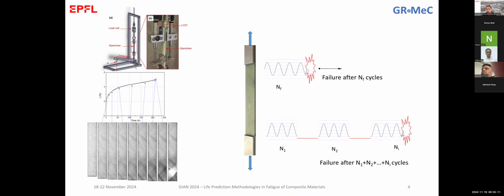So how are these getting together now, these three actually: the quasi-static testing, the fatigue testing, and the creep testing. This question is more or less responded to or visualized in this simple diagram that I have here. First, we see the one on the top. Imagine testing this specimen at a continuous constant amplitude fatigue until failure. Then it fails at a certain number of cycles.